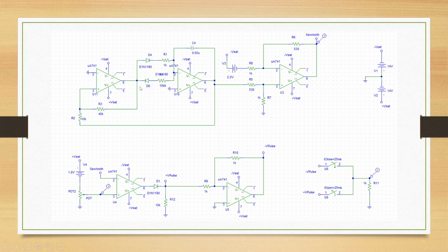The resistors in the circuit are selected to regulate the current flow during the rise and the fall intervals. When the waveform is rising, the current flows through one specific path with a control resistance value ensuring the steady and gradual increase. On the other hand, during the falling interval, the diode switches the path, allowing a much faster current flow. This abrupt change creates a steep drop in the waveform.